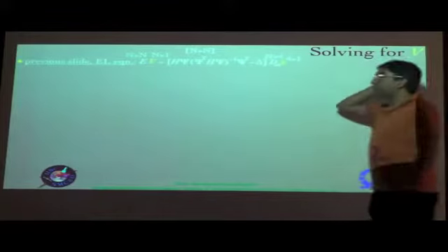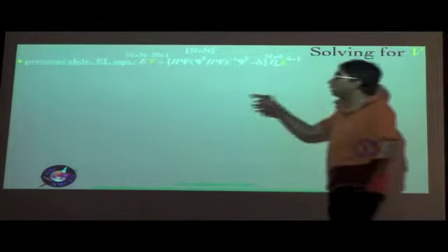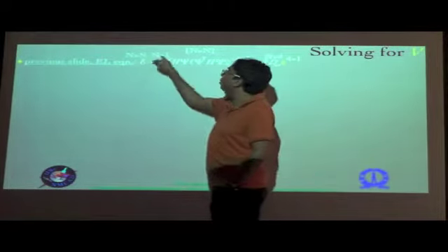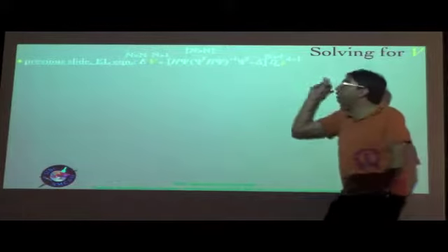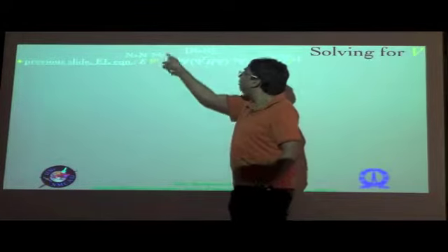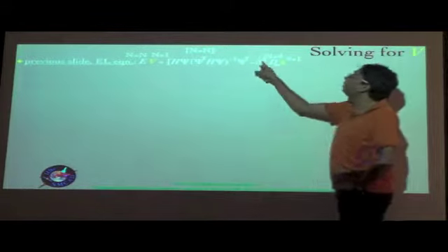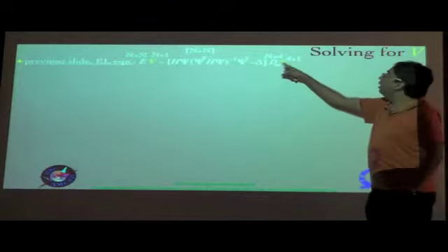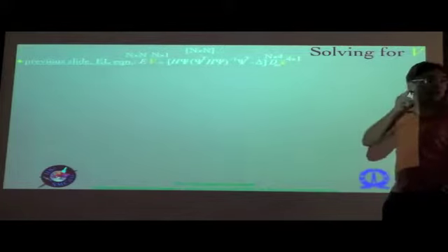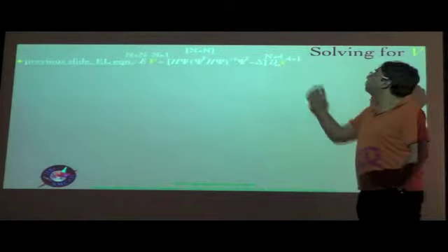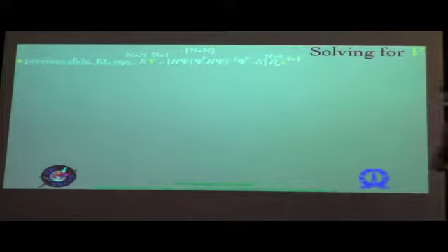From the previous slide, we're just repeating this, and now explicitly stating what the orders of each of these matrices are. E is n by n, V is n by 1. This coefficient that you have is n by n, including this identity matrix as well, and then an n by 4 intermediate stiffness matrix dA epsilon, and of course your classical measures in a column matrix of size 4.